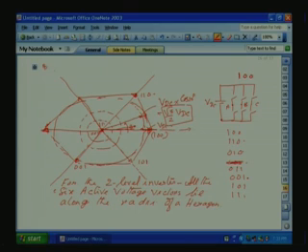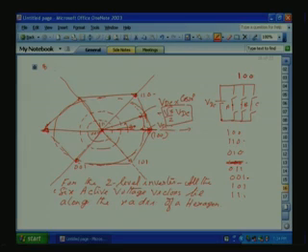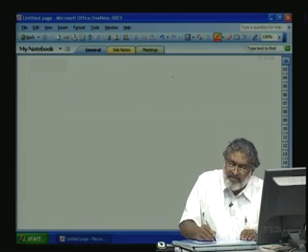Now, let us take a motor drive application, with the V by F control, which we will study later. As the frequency varies, the V also should vary proportionally. That means when the frequency is 0, V should be 0. When the frequency is 25 and then 50, the frequency is doubled. So, the amplitude or the radii of the voltage reference space vector should also be doubled. That means within this hexagon, we should have different inscribed circles with different radii possible. Now, how to generate? Let us draw our hexagon once again, approximately.